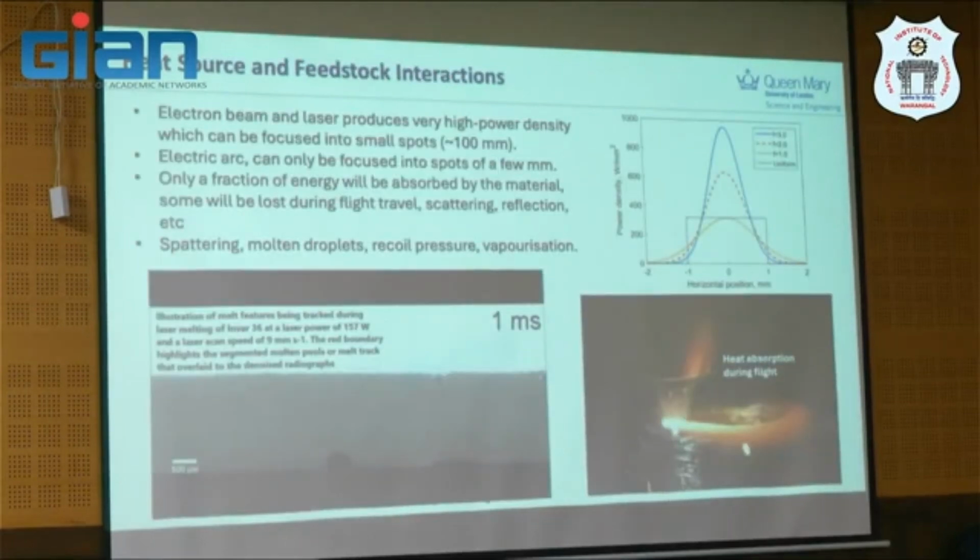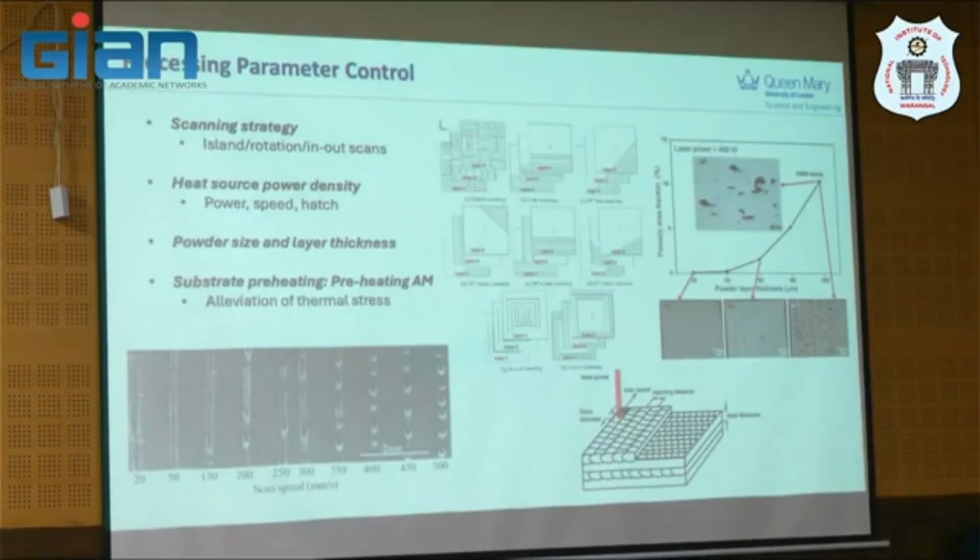I'll show the heat source model later. Another important thing is the scanning pattern. I just want to say the influence of this is also published in our process parameter work. You see here, this is a smooth track, but if you increase the speed a lot, a balling effect takes place, and this actually contributes to print quality. The scanning pattern also contributes to the final product.